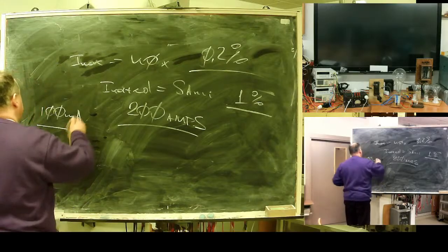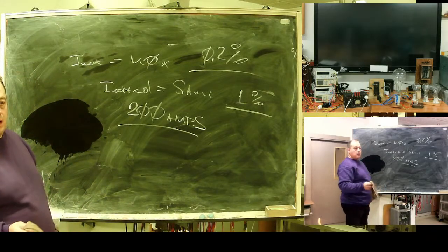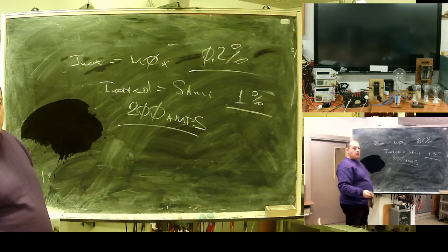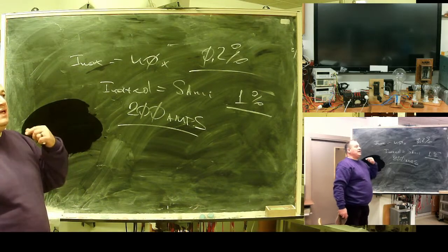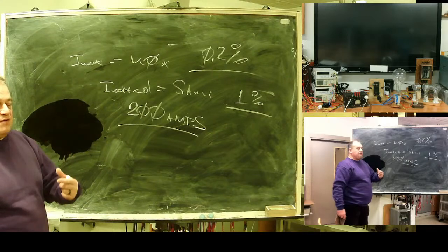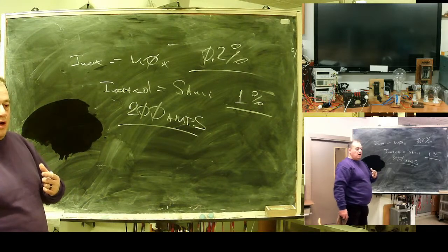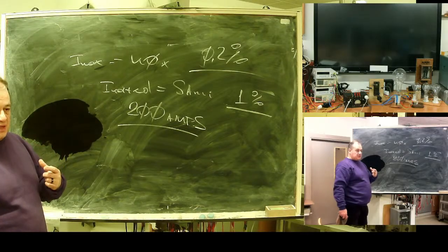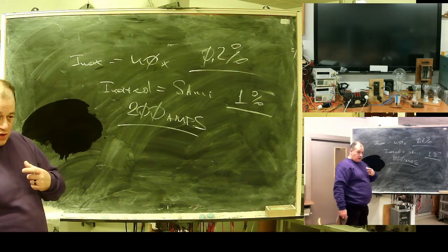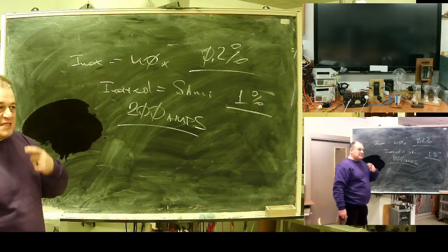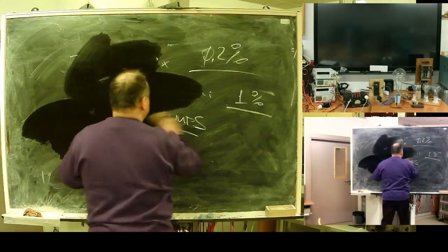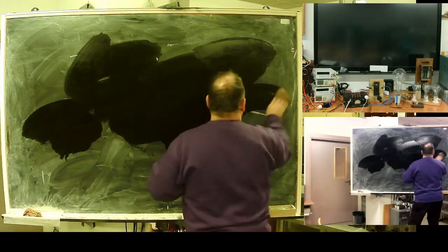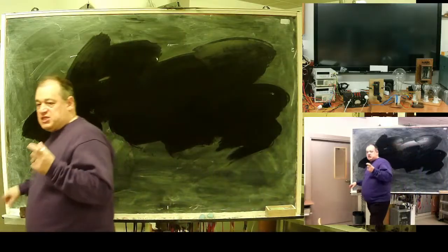Need to understand. I never got this. Why can lower amperage also be dangerous for the device? It's not dangerous for the device. It's that we cannot sacrifice precision in a small signal. The problem is that we can have a high impedance fault with quite low fault current, and we need to still be precise. A wide range of high precision.